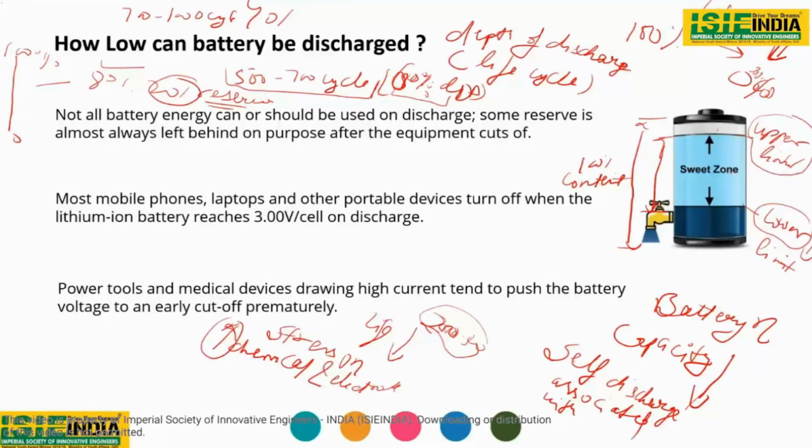The capacity of the battery will not fade at a very fast rate, although it will fade with every usage. But if you follow this depth of discharge, the rate at which it fades will be reduced, and the battery backup and the efficiency of the cell are going to last long. So this is the advantage of operating in the sweet zone.